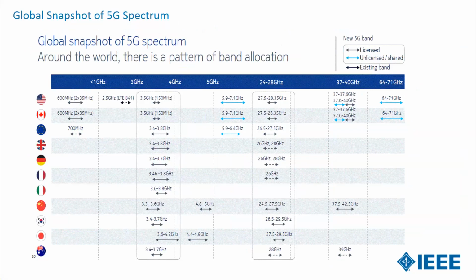I didn't talk about the actual frequency band, right? I spoke mostly about millimeter wave, but around the world, people have different frequencies. You see some of the millimeter wave bands like 24, 28, 37, 40 GHz, and people are getting into terahertz type spectrum with dynamic spectrum for 6G. And in some cases you have low band or mid band, and that gives you lots of range. But the millimeter wave gives you low range but high bandwidth. So depending on the suburban, urban, or city area, you can decide, right? Each country has its own regulatory aspects too.